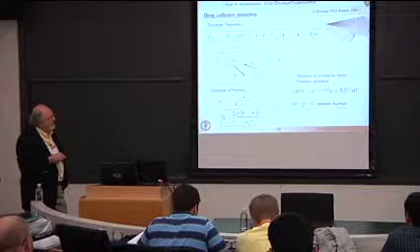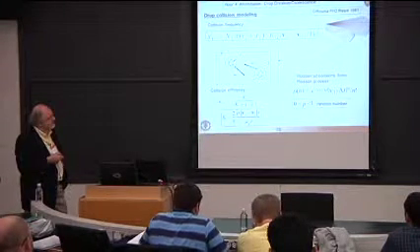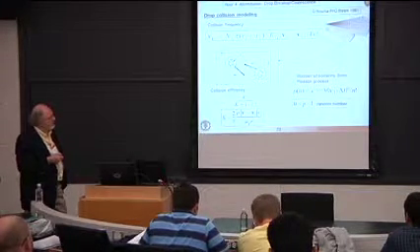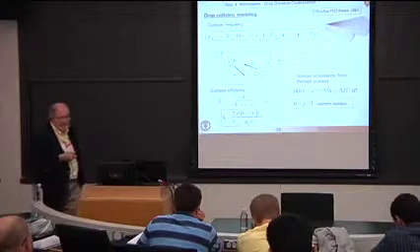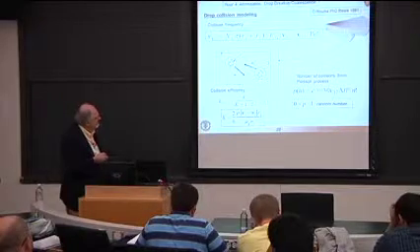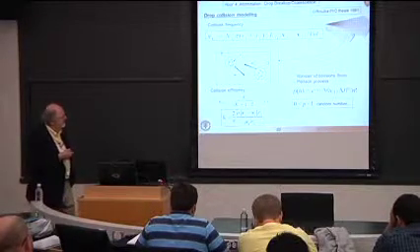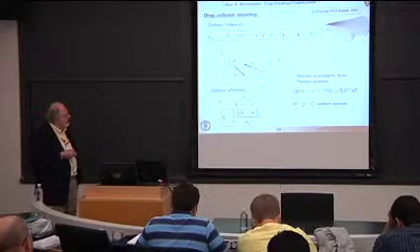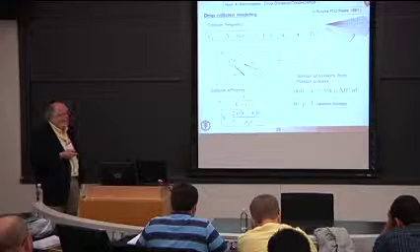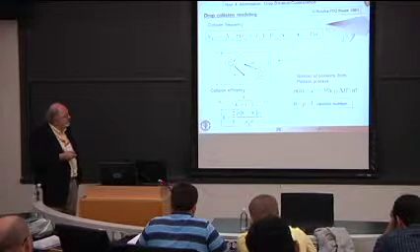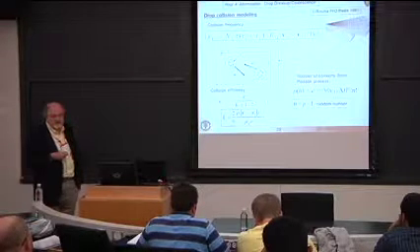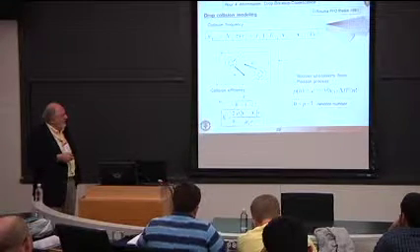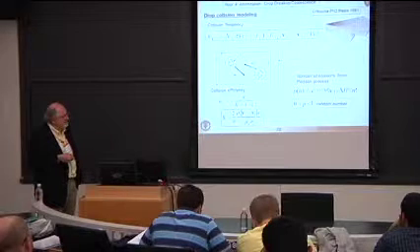And then finally, we have the vector difference between the droplet velocities and the volume of the cell in which these droplets are located. So that's a calculation of the collision frequency. So in order to use this in a stochastic simulation, what Peter O'Rourke did was to say, all right, let's consider this to be a Poisson process. The collision frequency is shown here.